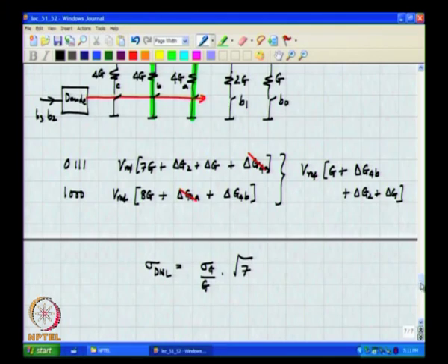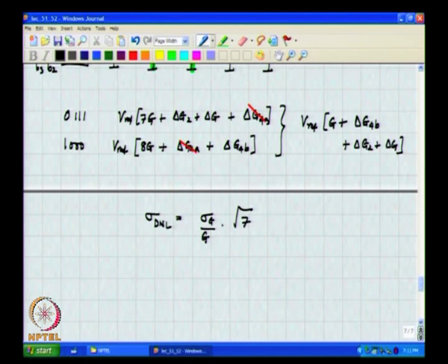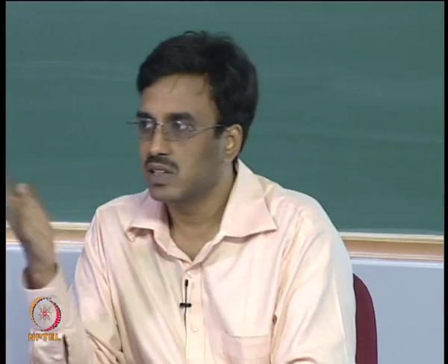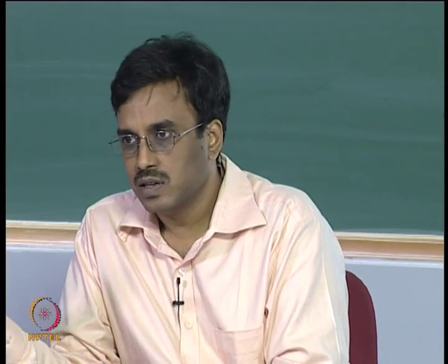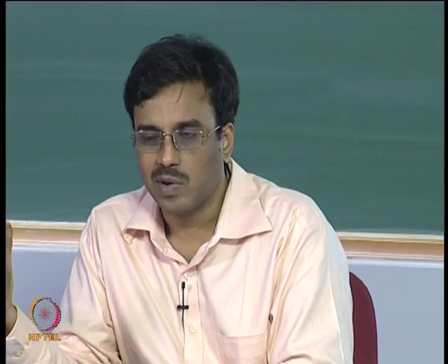Right. So, what can you say about sigma INL? Sigma INL remains the same. Okay. So, if you segment too little, what does it mean? Pardon? Yeah. So, as you keep changing the degree of segmentation, which is defined as the number of bits, clearly it is established that it makes sense to make the MSB portion thermometer coded and the LSB portion binary coded, or binary decoded rather.